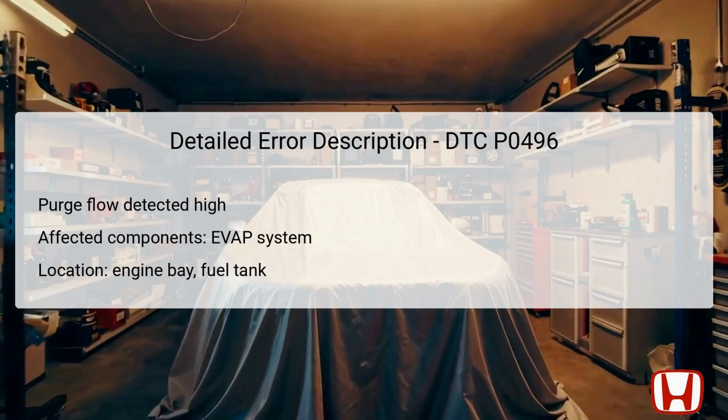The primary components affected by this issue include the EVAP canister purge valve, which is responsible for regulating vapor flow from the EVAP canister to the engine during specific conditions. Additionally, the FTP fuel tank pressure sensor may contribute to the readings that influence the diagnostic function. This FTP sensor is typically located at the fuel tank, monitoring pressure changes due to fuel vapor levels.